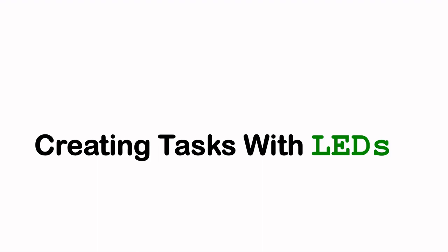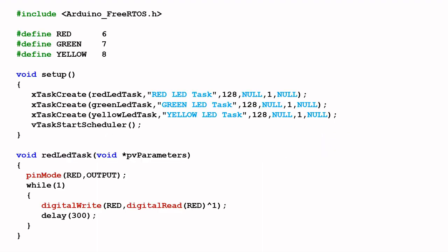Creating tasks with LEDs. All right, this example demonstrates how to use FreeRTOS to create tasks to control 3 LEDs. So here's the sketch, and we start off by including the Arduino_FreeRTOS.h header file.